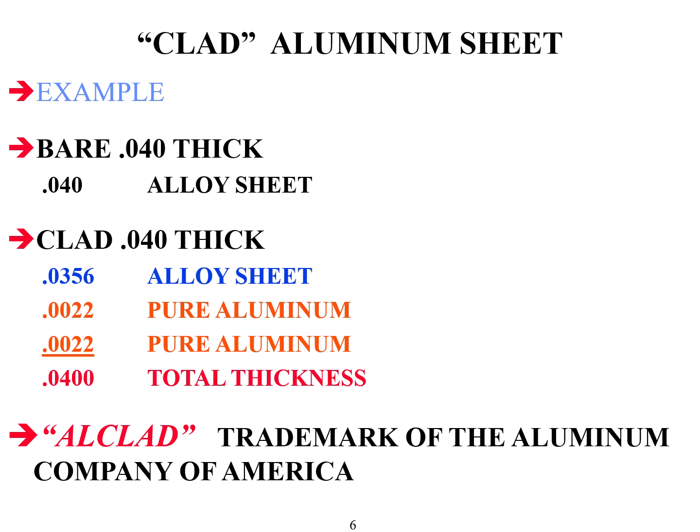So the big thing there is if you're working to repair an all-metal aircraft, the FAA question is, what type of metal would you use? Well, we always use the same as original or properly altered. So if it's clad that we're repairing, we will repair with a clad piece of material. And often you'll see terms like Alclad.